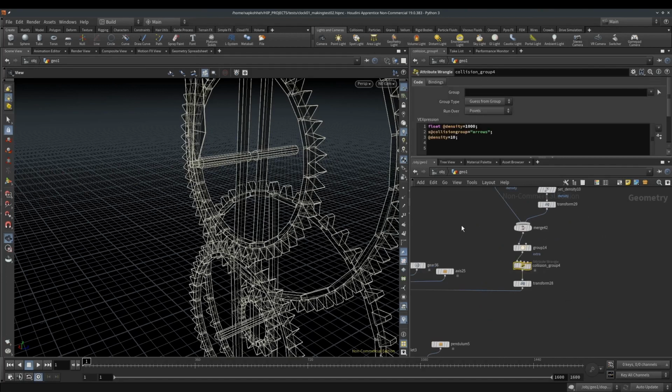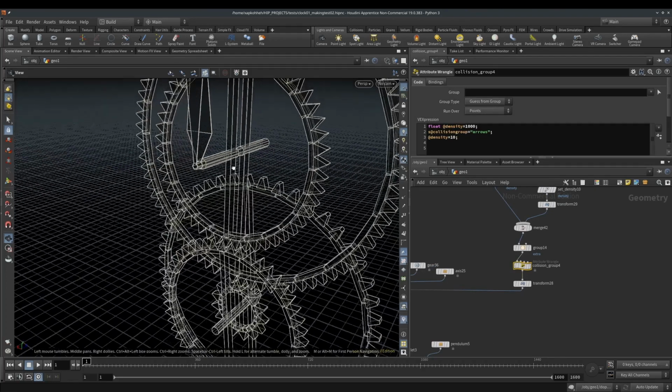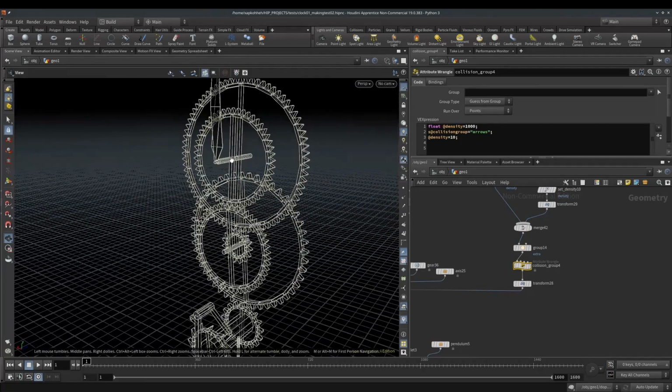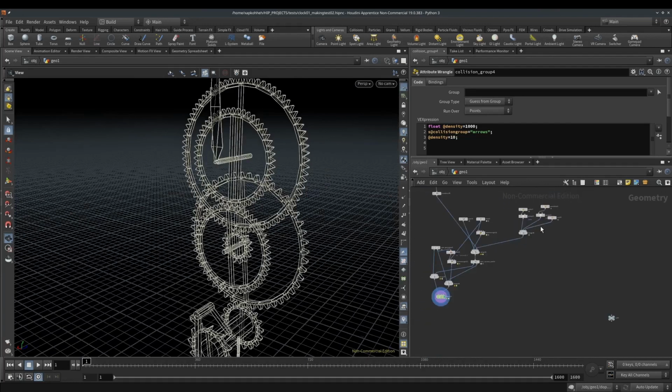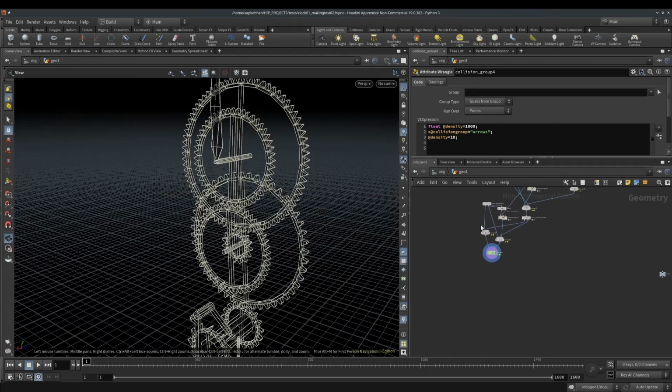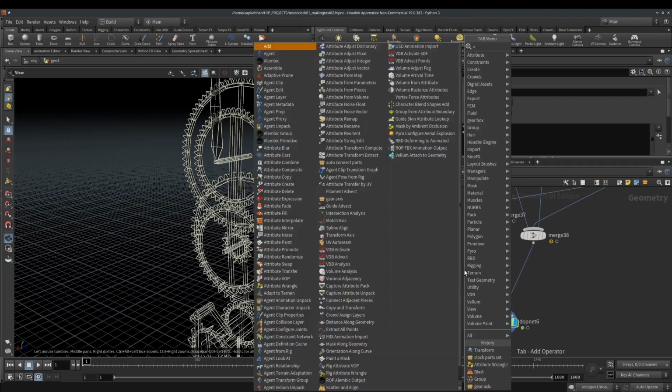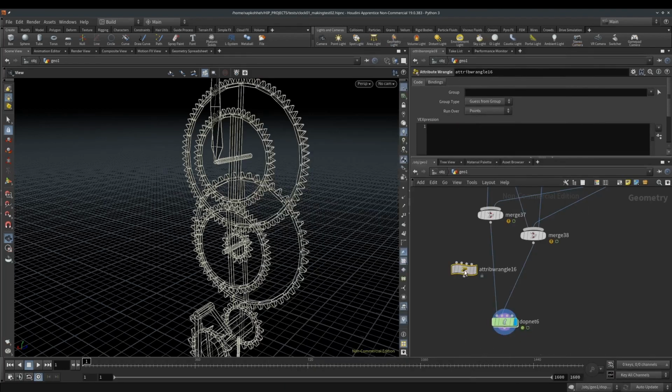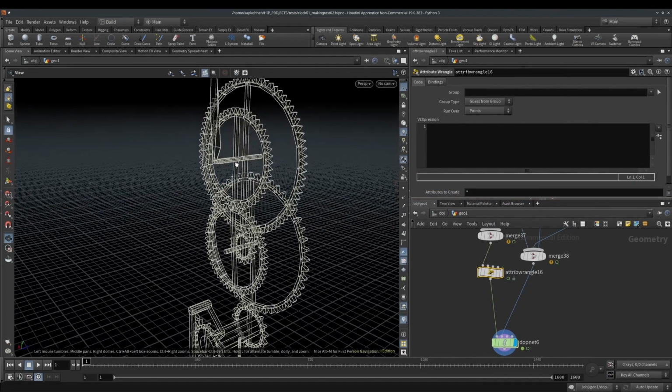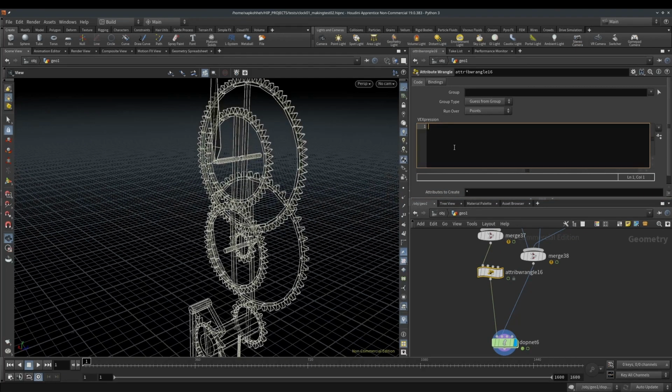we will set them to the collision group of arrows. And you also see that I set their density to be 10, so they're very, very light and don't really affect any other parts of the mechanism, so that you don't think that the whole thing works just because the heavy arrows are pushing on things. So here is a little trick to make things not collide with arrows and arrows not collide with things.